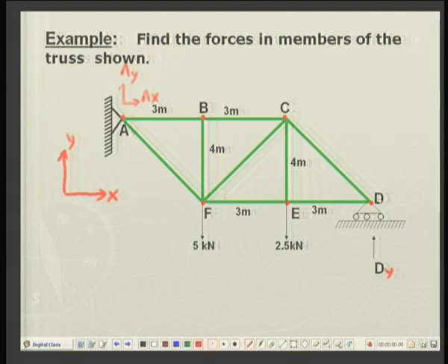Okay. Now, if I go back to this joint, we have already found out Dy. Now, as a check, do we get this condition that the component of the force in TDC is equal to the applied reaction and the calculated reaction Dy? If the check is okay, it means our whole analysis was okay, no error was committed. So, let us see.